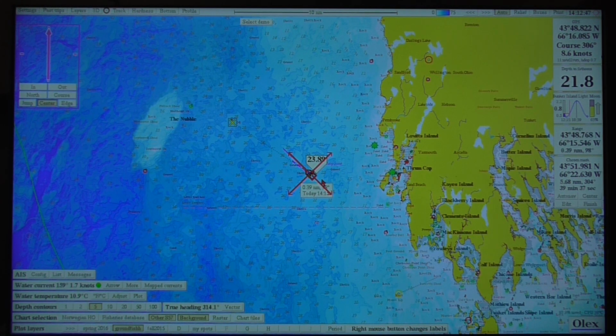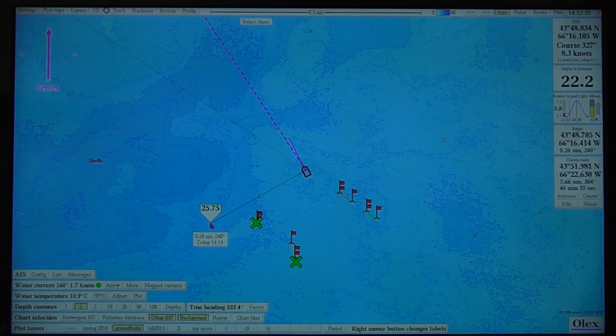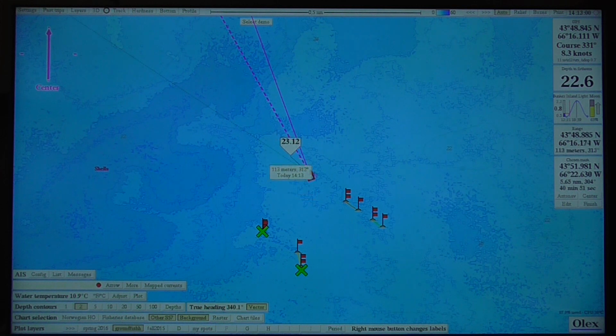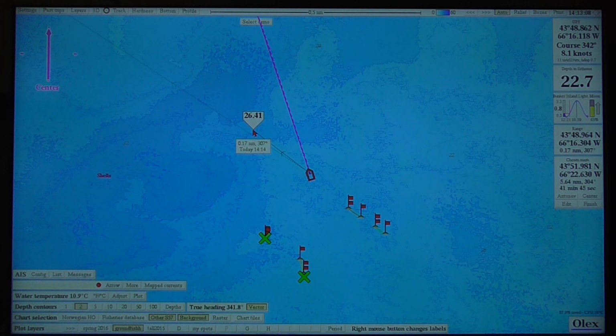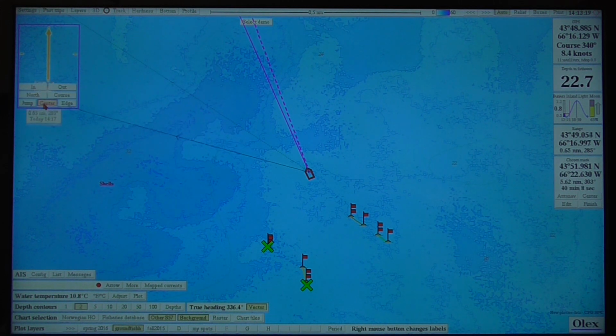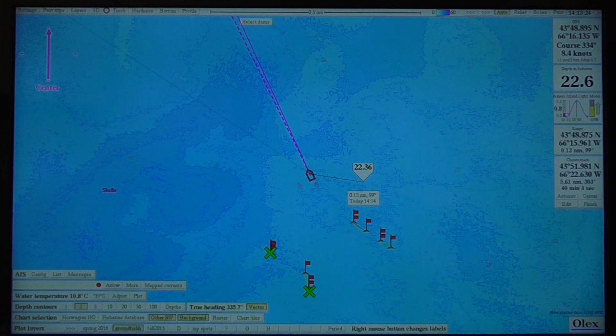So if we center our boat, here's our vessel sailing along. We see two vector arms off of this particular vessel because this vessel had a satellite compass or gyro on board. So what we have is our dotted line, which is our course over ground, and our solid line is the heading, or the way the boat is pointed. Interesting, when you have both, you can get an idea of tidal drift or currents, how they're pulling the vessel. So if you look here, you've got center boat, which basically keeps the map moving and the vessel in the center.